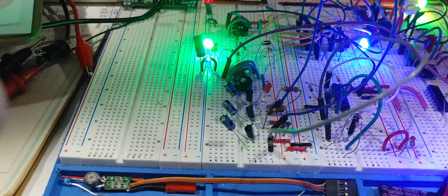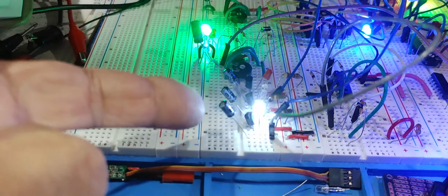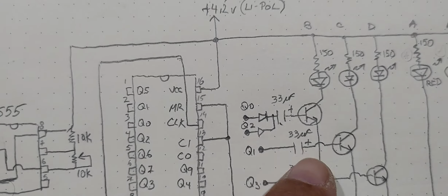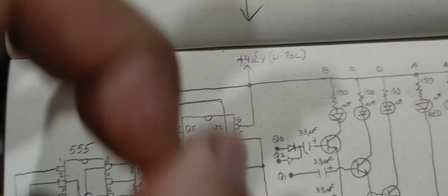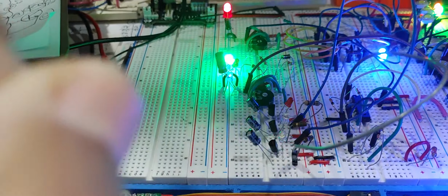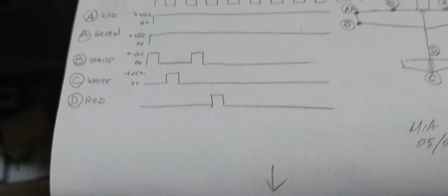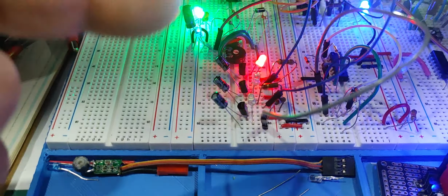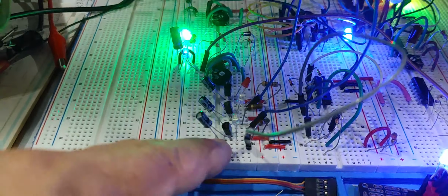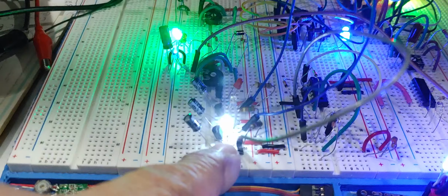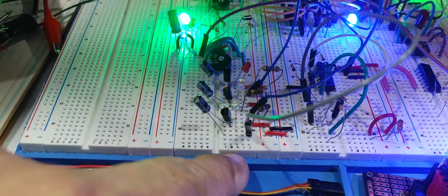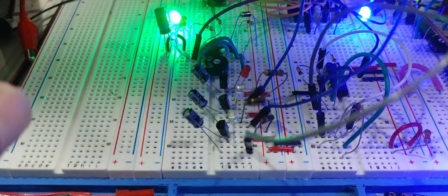You're not using the full intensity of the LED, and so I am using external circuits here with some transistors and capacitors to amplify it and give it, more than anything, that strobe effect, that goes on and off, and that's due to the capacitor and resistor combination associated with these transistor circuits. And so that's what's giving it that effect, and as you can see, it's working out really nice.